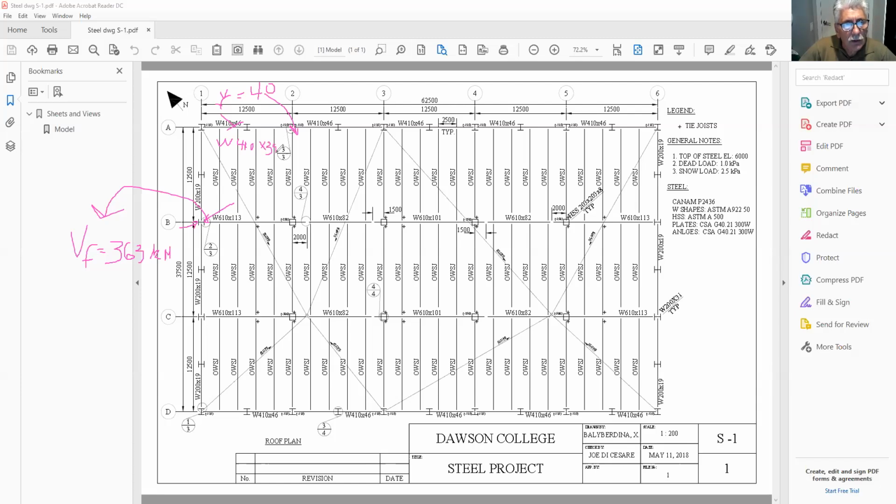That's the beam here. And because here what's going to happen is that the double diagonal connections are going to have to fit inside that column. And of course, since you have 40 on that side of the column, when you're checking the thickness of the web here for the column, you also have 40 there. So that's something you have to keep into consideration.